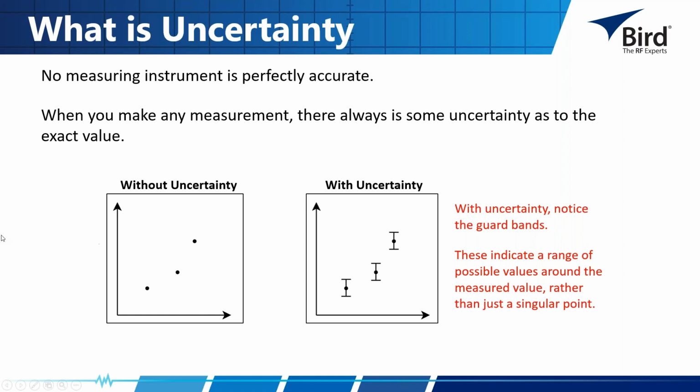So what I'm saying with that is the idea of the measurements without the uncertainty taken into account, like here, where we can see it's just more of an absolute point that we're putting down. And then when we're looking at uncertainty, we actually take into account a guard band to help account for these different variables, whether it's a measurement device or something to do with the system.